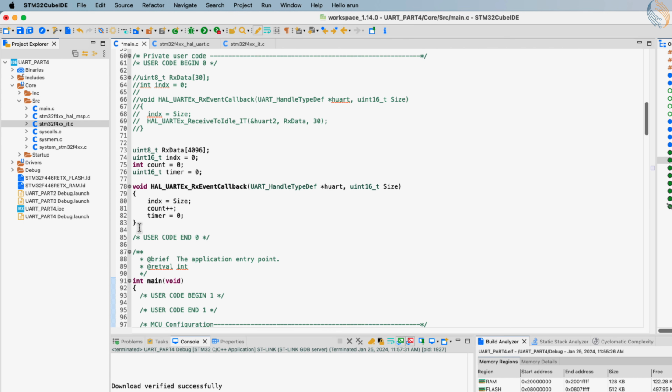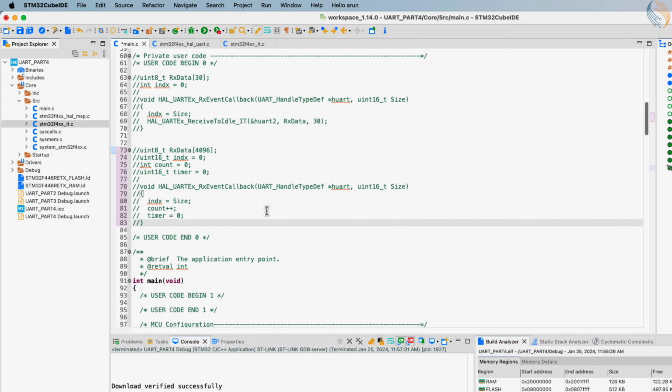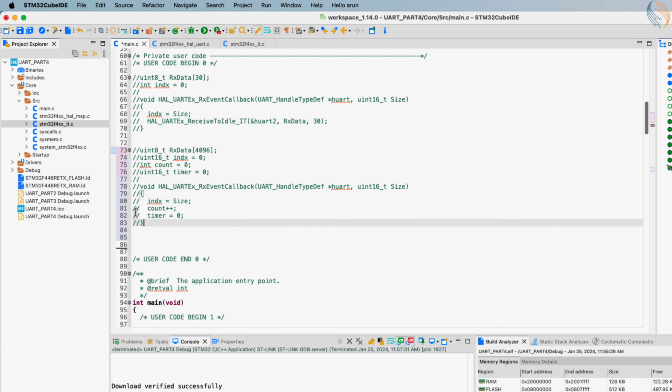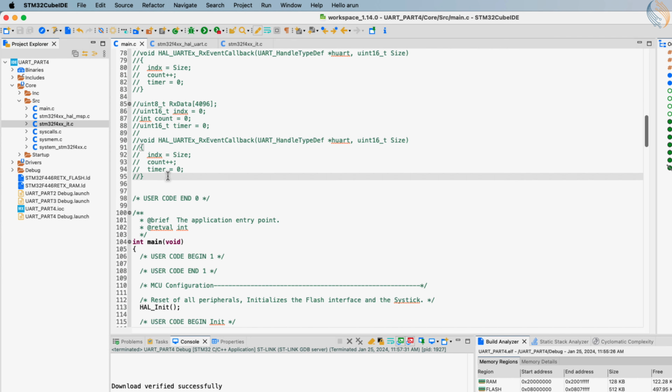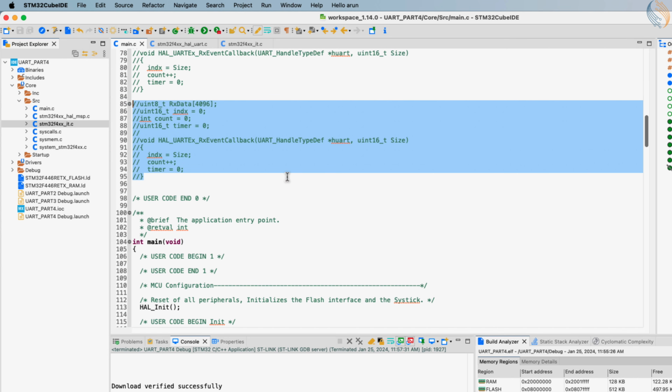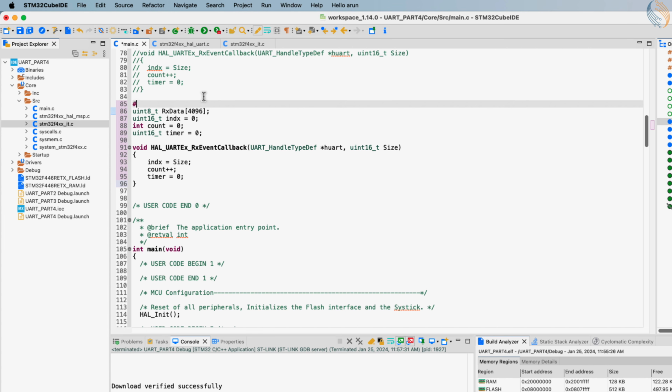But what if the data is huge, say in megabytes, and we need to store it in the SD card, or a flash drive? We can't store the data in megabytes in the RAM, as most of the MCUs do not have enough memory for that. We will use a small buffer to receive this data, and then send the received data directly to the file. I am writing a separate code for this section.